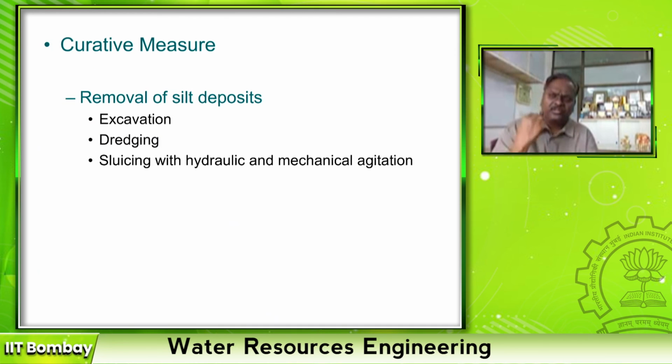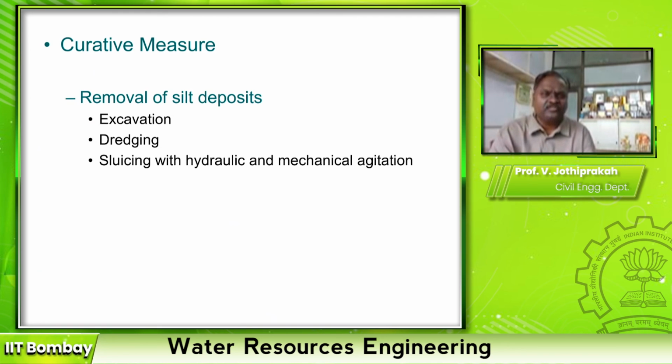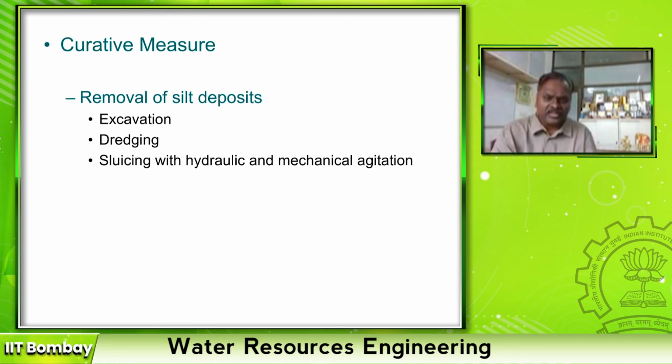Curative measures mean that even with all these, sediment is still depositing, so you use manual excavation, dredging, right? Or sluicing with hydraulic and mechanical agitation. These are all some of the curative measures to remove the silt deposited in a reservoir, right?